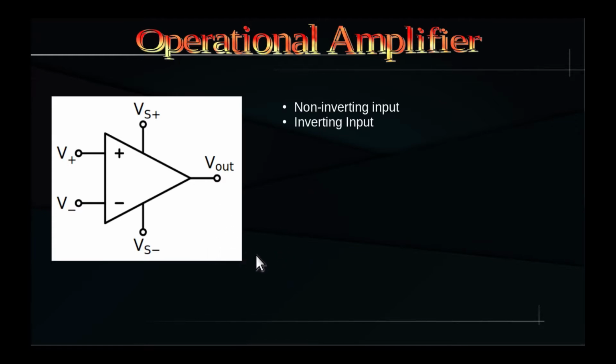These devices are usually powered with two separate voltages, both measured against the ground. Powering them this way allows us to deal with analog signals that can be both positive and negative with respect to the ground, without the need to use capacitors to decouple these signals from DC.